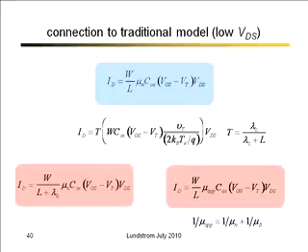We can think about using the traditional expression with the physical bulk mobility and just thinking about the device never being shorter than a mean free path. You might ask, why, when the channel length gets very short, is there a mean free path in this expression? Because it should be ballistic. Well, there's a mean free path in the mobility. The two cancel out.